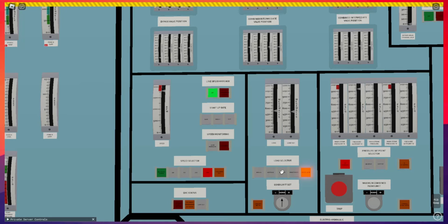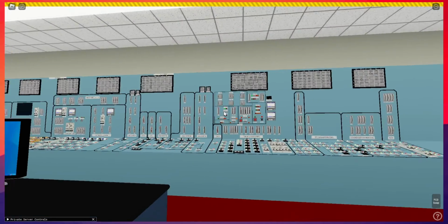We don't want to generate too much stress on the reactor, the turbine, and the balance of the plant, because doing this actually does affect reactor power. Again, more steam being drawn decreases and increases pressure. That creates an oscillation in power. Pressure affects power in boiling water reactors. Not a lot, but enough for it to be noticeable.